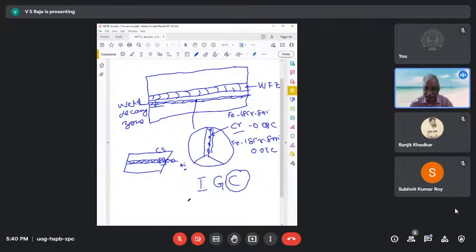That is not to be confused with intergranular corrosion, right? That should be seen as an improper heat treatment. Because of the load that is applied, because these are all precipitates at the grain boundary, they cause the cracking along the grain boundaries. That is something like decohesion of grain boundaries taking place, and so there is going to be intergranular cracking. So it should not be confused with intergranular corrosion. The intergranular corrosion comes because of chemical variation, what you've seen in the case of sensitization. Okay, so they can be entirely different.